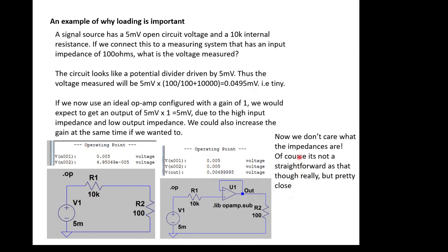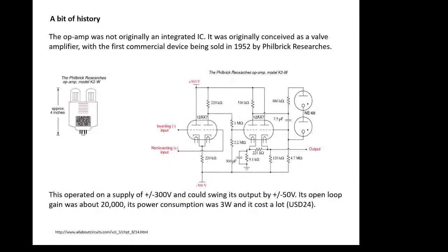And the nice thing about this is now you don't care what this value is, and you don't care what this value is, because you've buffered it in here. And that's the power of putting buffers in the way. Suddenly you don't care about what the rest of the system is doing because of high input impedance here and the low output impedance here. Okay, so I hope that clarifies things about why impedances, output impedances, input impedances are very important. It's quite a simple case, but it's something that people seem to forget all the time.